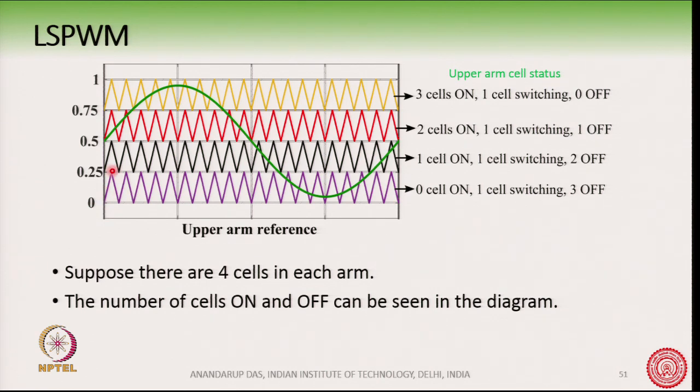these carriers here, so when the waveform, suppose let us take this portion of the waveform. Let us first concentrate on this portion. On this portion, what we can observe is that in the power circuit we are trying to fabricate this part of the voltage waveform. So, from the arm we are trying to fabricate this part of the reference waveform. Ideally the actual arm voltage in the power circuit should be an exact replica of the reference voltage, because when we give the reference voltage we are asking the arms to produce exactly a replica of it, but amplified in the power circuit.